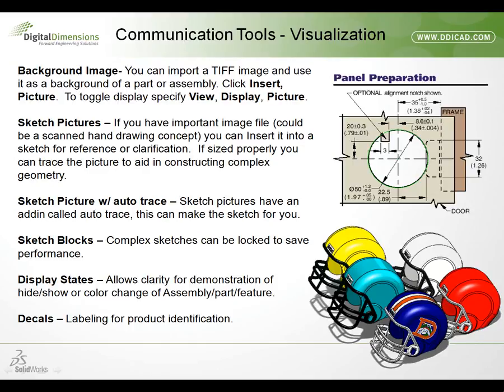Now, the image set in the System Options will be overridden by this background image TIFF that you drop in here. The primary difference between this and the image that you would set in the System Options color image is when you go to send this file out to a client, this TIFF file is embedded into the SOLIDWORKS document, so as long as their system settings are set to Plane, Gradient, or Image file, they will see your TIFF file in SOLIDWORKS.